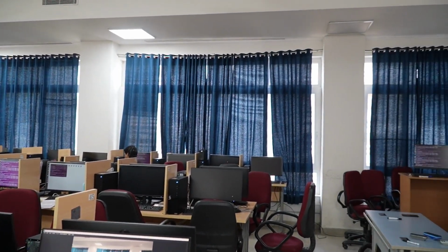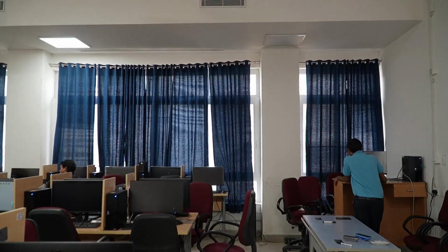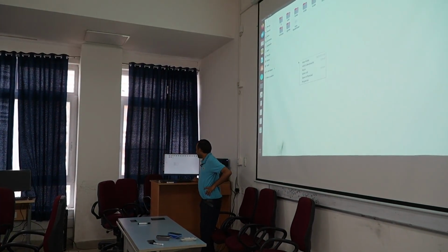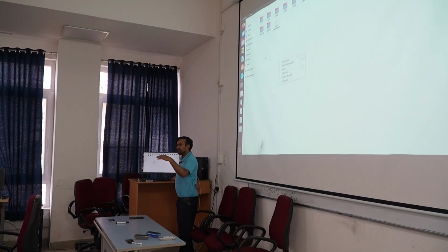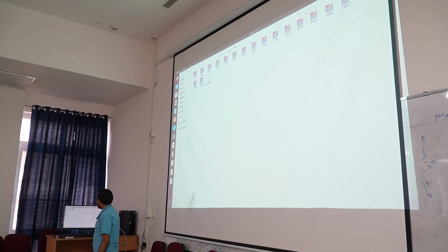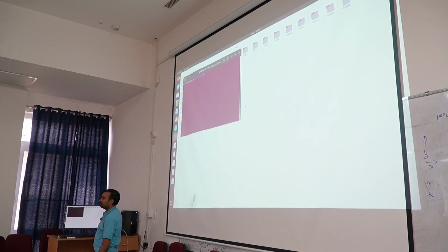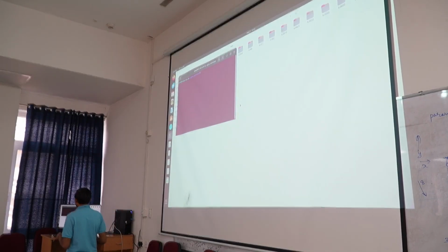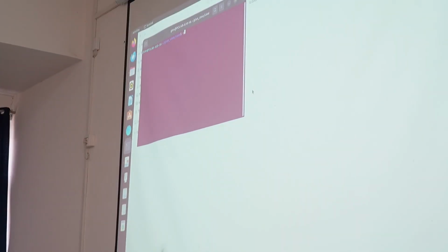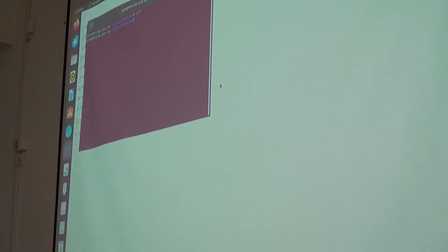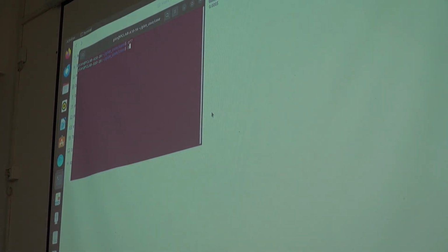Okay, so probably the grid is very fine, so it will take time. Instead of waiting for this, it has created a good number of files. So I can keep this terminal running, enter the main folder, and click on a new terminal. What I have done here is open a new terminal. Now through this new terminal I will again write OF7, because it's a new terminal. After OF7 I can write paraview.